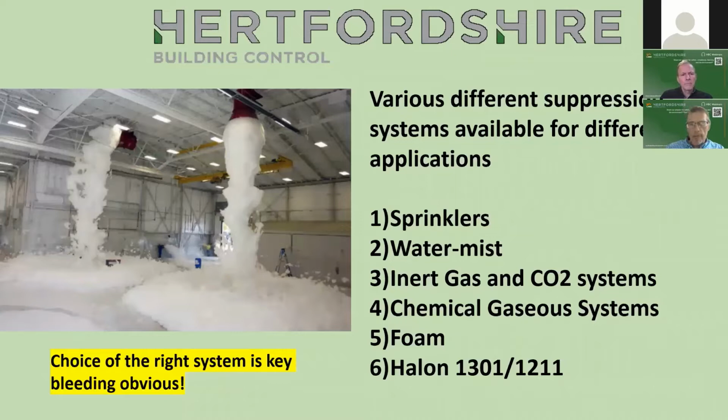So we've got various suppression systems available for different applications. We've got sprinklers, water mist, inert gas and CO2 systems, chemical gaseous systems, foam, and the outlawed but extremely useful Halon 1301 system, and obviously because that's an ozone depleting gas, it's effectively been outlawed.